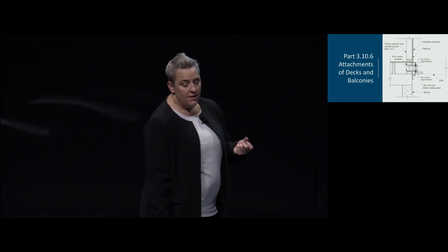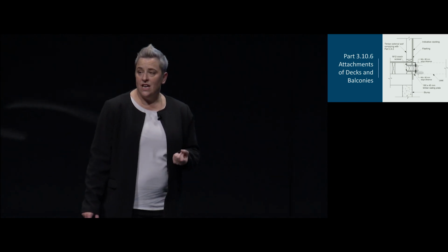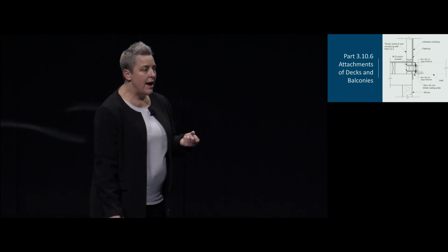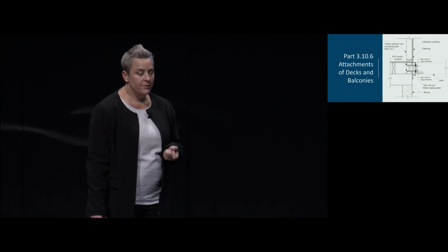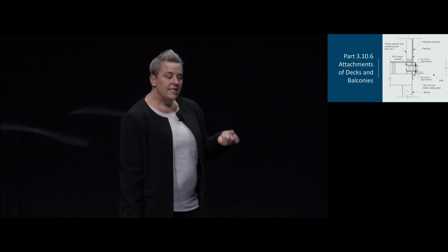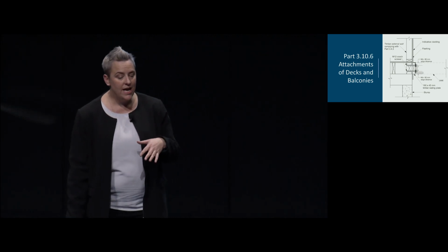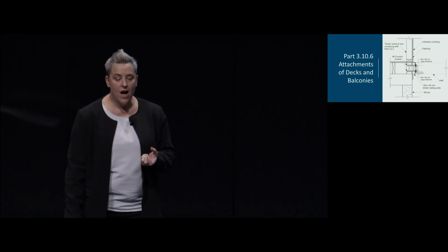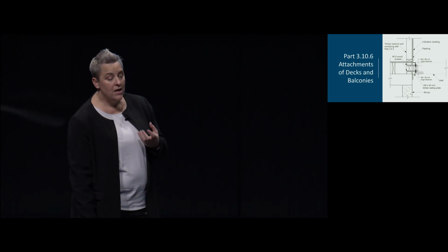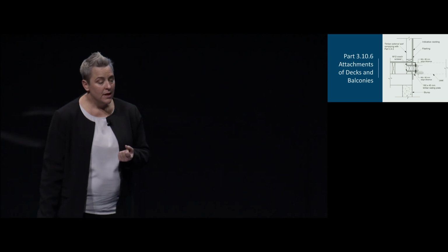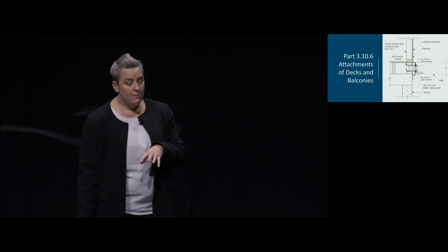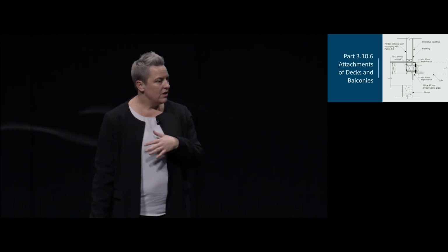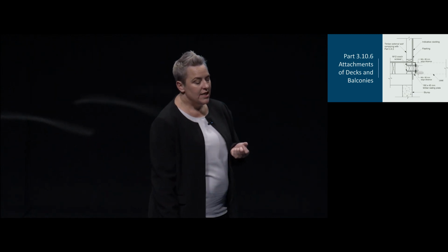So more than likely it won't be widely used in Victoria because we use a lot of masonry veneer construction. AS 1684, your residential timber framing construction, does not provide the details for your walling plates, and this situation would have required the design in accordance with Part 3.11 under the 2016 BCA. So typically it would have been produced by an engineer.